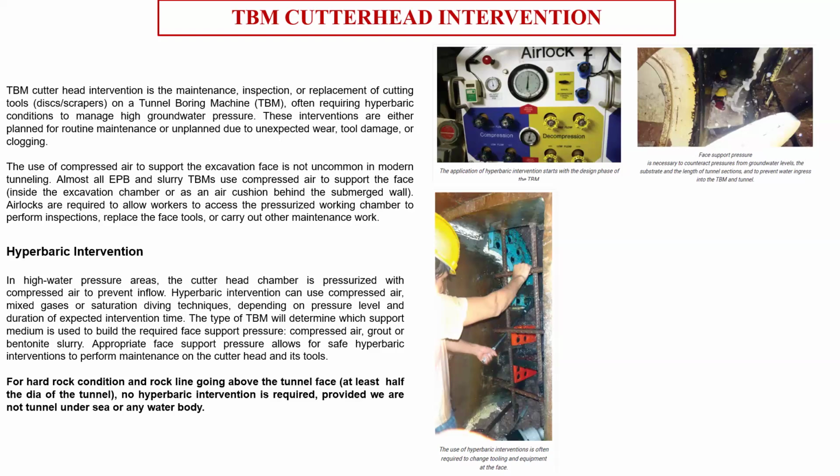So we applied thrust. The TBM shield was retrieved, but it affected the segment lying behind the shield, and we got a series of cracks in the crown. The cracks that appeared in the segment were not a design fault. It was because of the curvature; the TBM could not tackle the curve, and the segments being built behind the shield were also getting stuck.